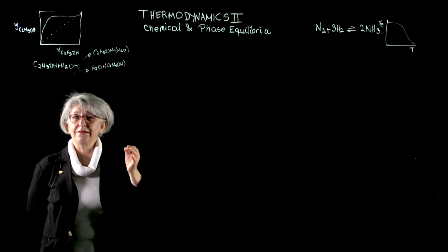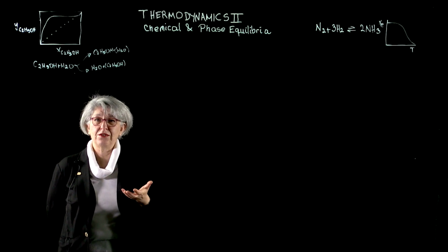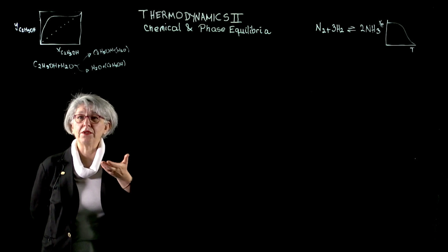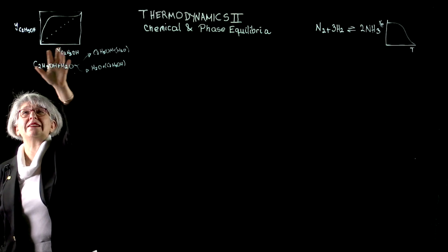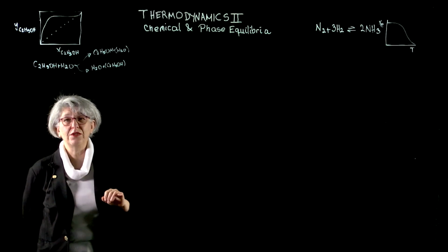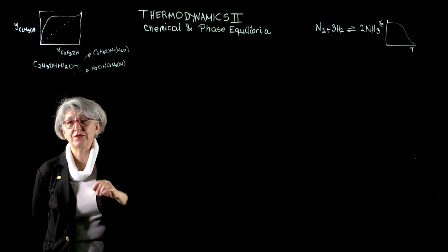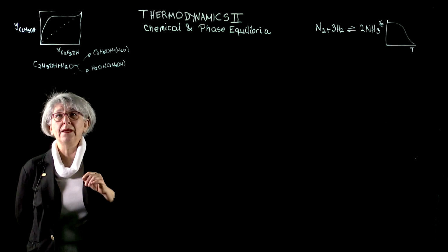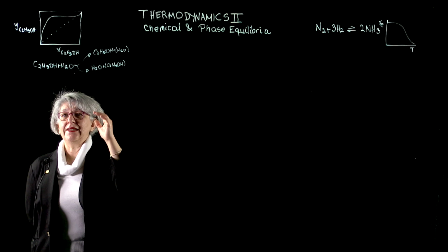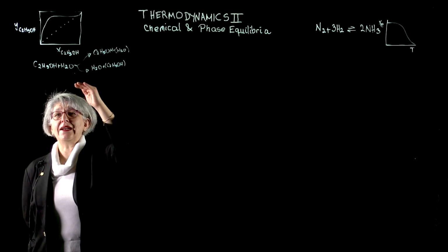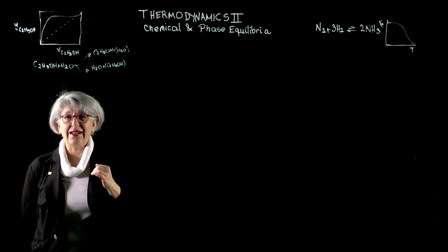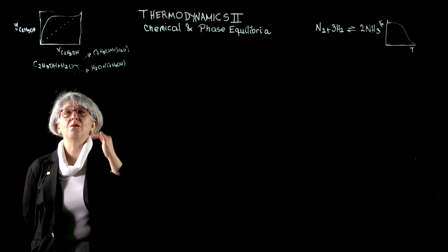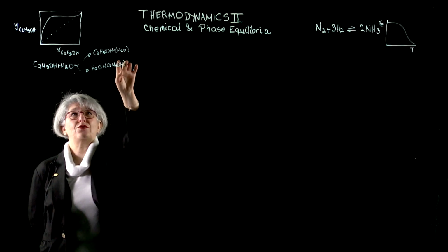As a result, we can boil the mixture, and the lower boiling component is enriched in the vapor phase, as indicated by the vapor-liquid equilibrium phase diagram you see on this corner of the board. And by carrying out cascades of operations, we separate ethanol from water to a certain extent.